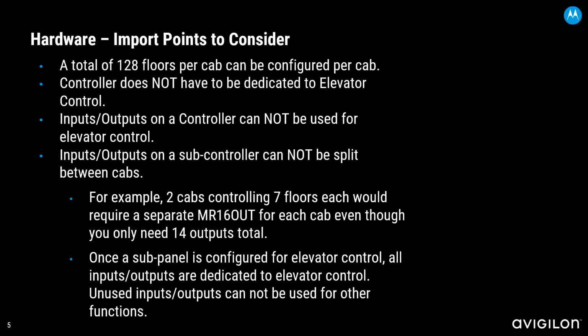Now, another topic that will come up: when you do dedicate a subcontroller to elevator control, the unused inputs and outputs cannot be used for any other functions. Can't use them to do an input for a door grant or an output for a strobe on a door or anything like that. Basically, that subcontroller can only do elevator control.